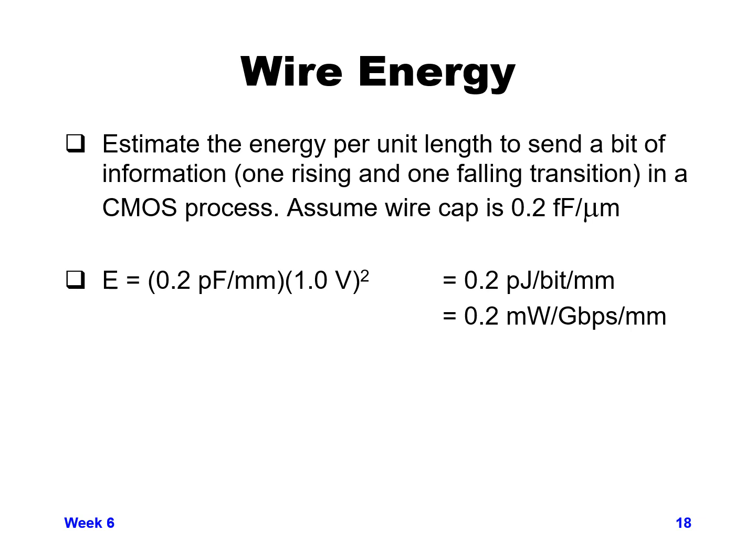And then if we have that running at 1 gigahertz or 1 gigabit per second, that will require 0.2 milliwatts per millimeter at 1 gigahertz. And so you can see that, if we have a millimeter long wire, 0.2 milliwatts doesn't maybe sound like a lot, but keep in mind that there's tens of thousands, if not hundreds of thousands of wires in your design, and so that can add up to multiple watts if you're toggling all your wires in your design at a gigahertz clock speed.